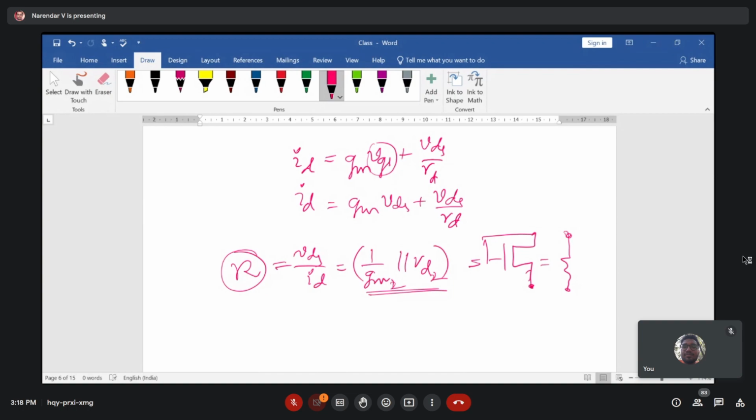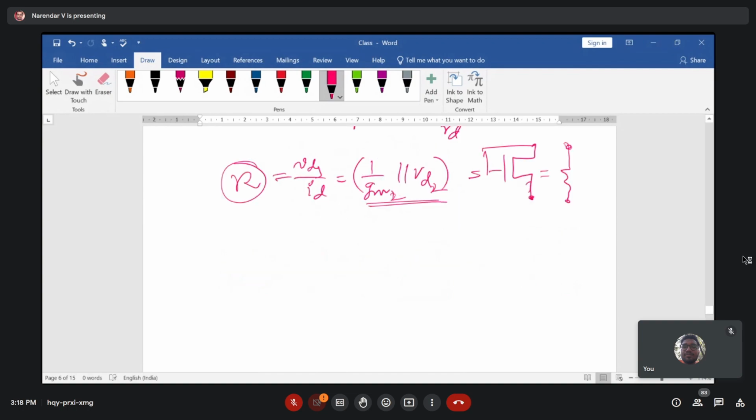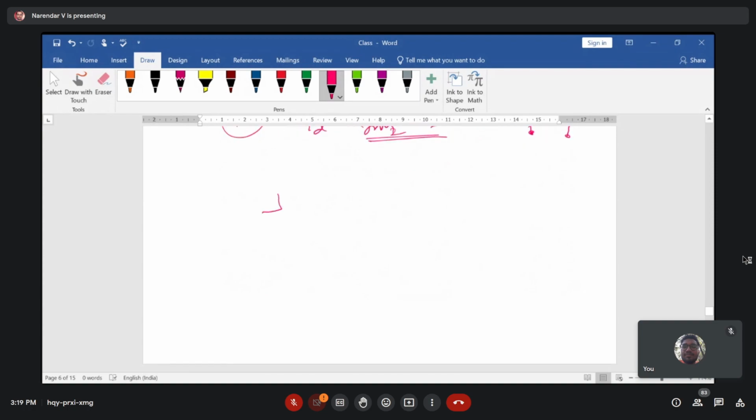Okay. So now if you consider that example, here we are eliminating the resistor and connecting a diode connected MOSFET. Let me draw the M1 transistor, which is the basic transistor, and then small signal DC biasing.